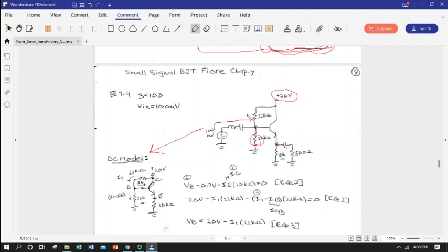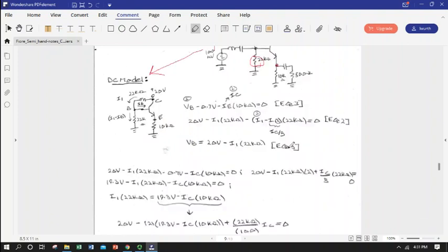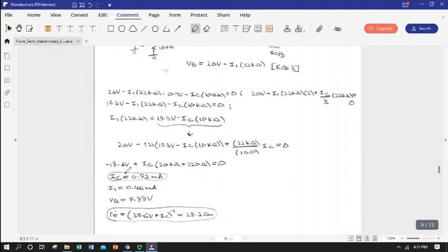So 10 volts minus 0.7 volts to get over the base emitter junction, minus our collector current times 10K is going to equal 0. And so that will give us our I sub C, and we can get fancy with a lightly or heavily loaded voltage divider, but we can generally assume that I sub B is pretty small. And we get, not surprisingly, a collector current of a little under a milliamp. We can also define all the other currents in that branch.